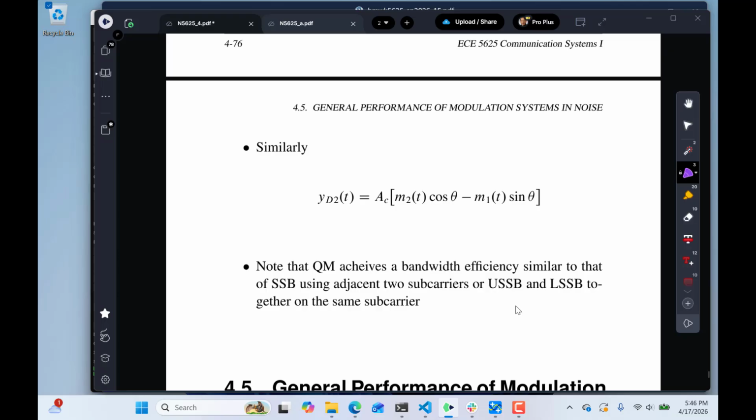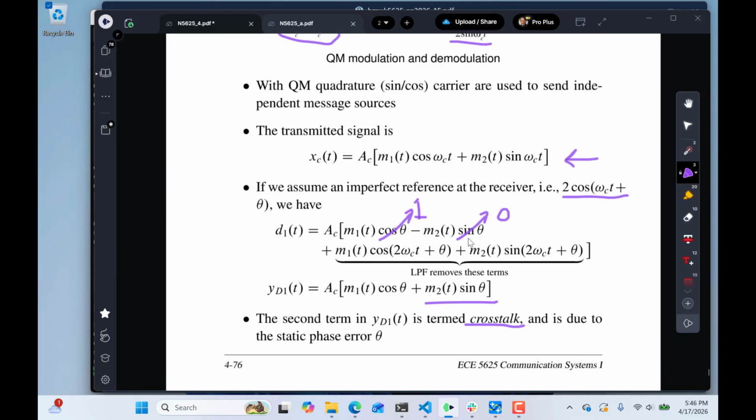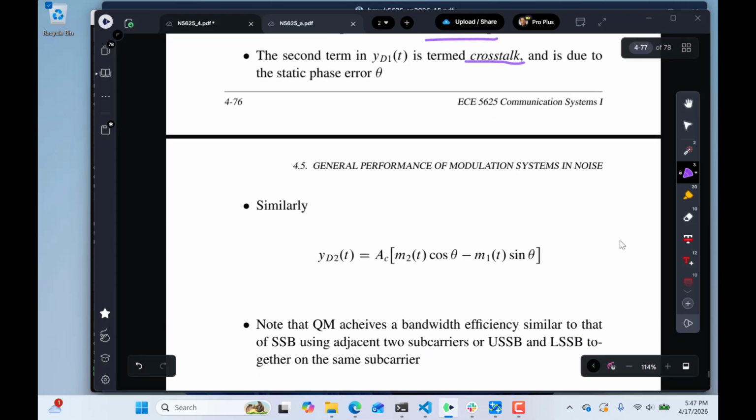You basically have 2 signals you're hearing mixed against each other, because just look what would happen here if theta is rotating slowly on the cosine. You're going to hear both signals mixed together. So you have to have perfect quadrature, and you have to do it coherently.